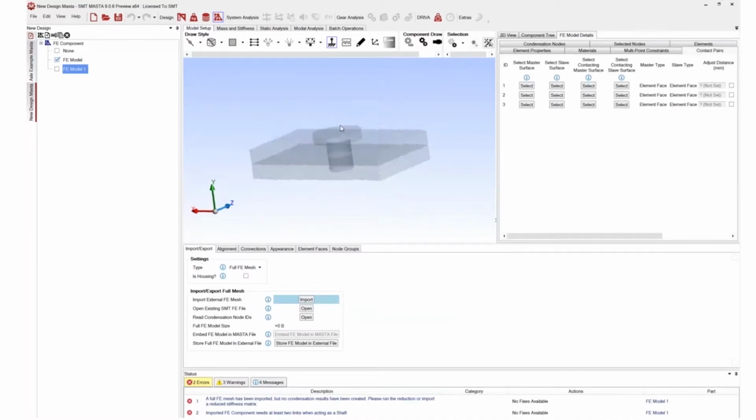The second model, we can see we've also got the shape of the bolt in there, so we haven't bothered going into detail on the shape of the head or the screw thread or anything. We've just modeled it as two cylinders effectively. So we've also introduced additional bonded connections underneath the bolt head, and also where the thread is connected to the lower surface. And as before, we've still got the bonding between the two surfaces as well.